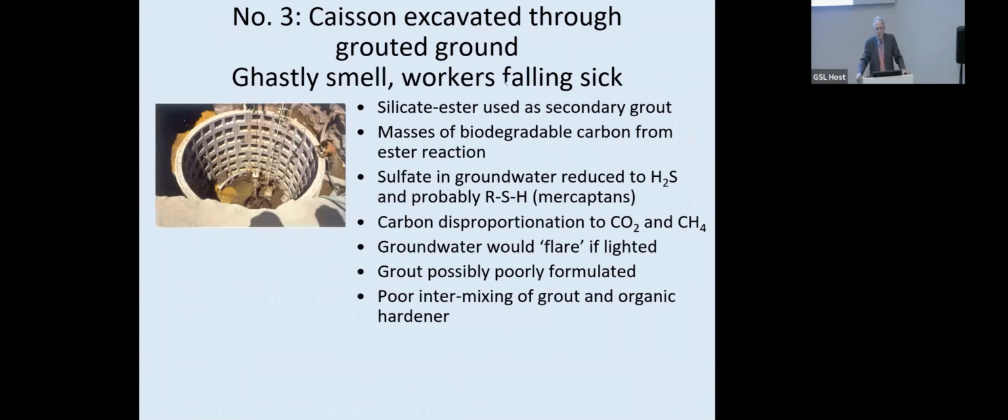But was it the ester that caused the problem? So years later, we come to a caisson excavated down through grouted ground. This was going to be a compensation grouting job, cement grouting and silicate ester as a secondary grout. And I was called in because there was a terrible smell in the caisson, really, really grossly unpleasant. So, and people were falling ill, some with septicemia and other things. I think the septicemia was a completely different issue.